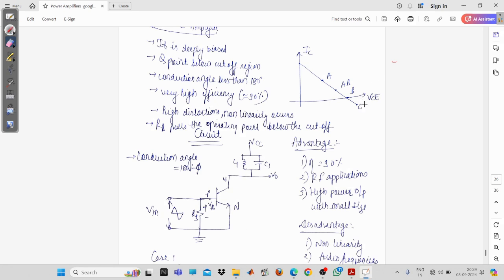Normally, we will always place our AC signal onto the DC operating point. So in that case, your AC will get amplified. Now, where is your operating point? Your operating point is in the deep cutoff. So what is going to happen? I am going to place my AC signal. So you can see that only some part of this signal is in the active region,